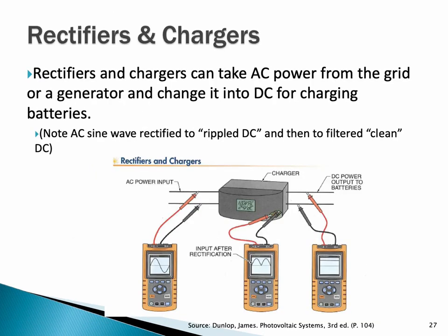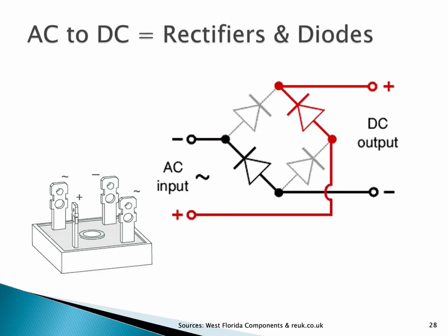When we do that, these rectifiers use diodes to cut the sine wave in half, and then the opposite direction flips that sine wave into the upper layer, the positive side of the zero line, so that we have a constant pulse of DC. So we're converting that AC into a DC signal, flattening it out into a constant voltage and current output. And that's with diodes.